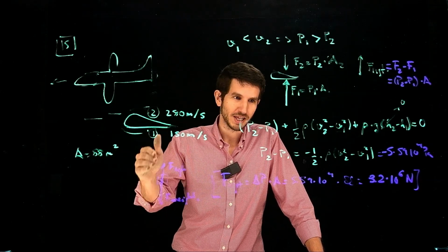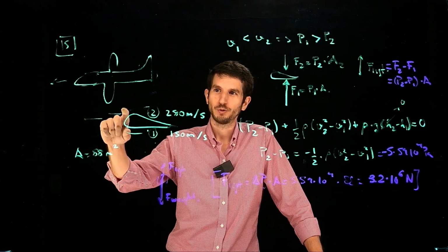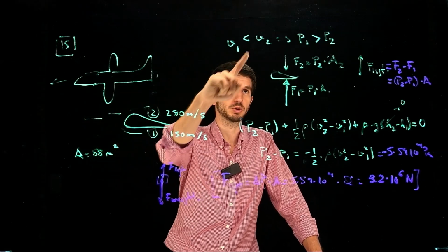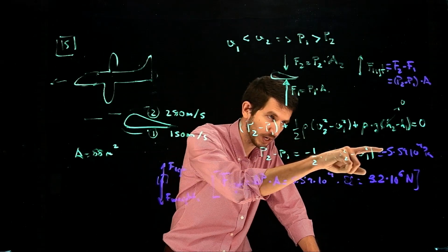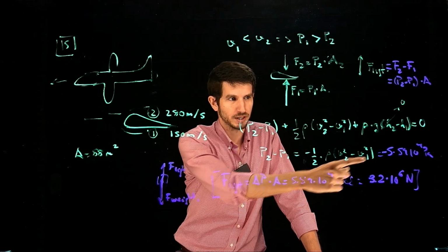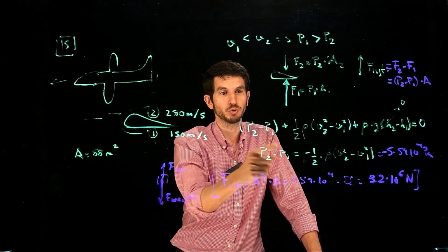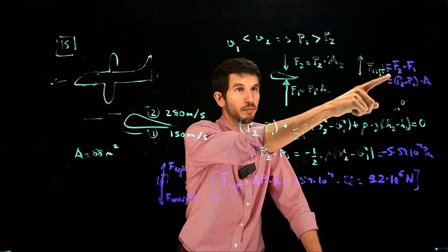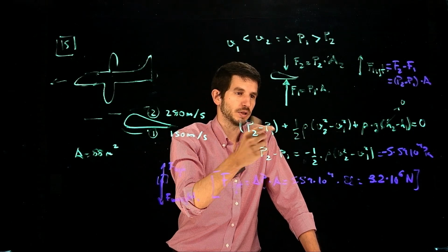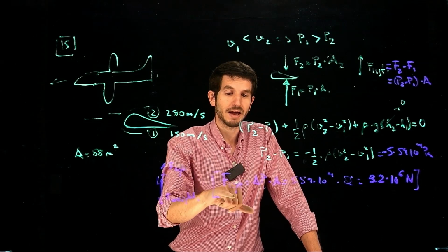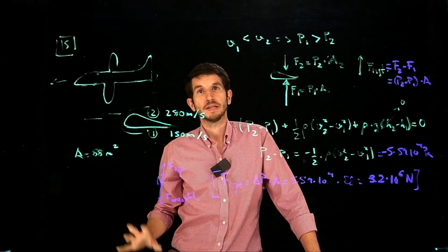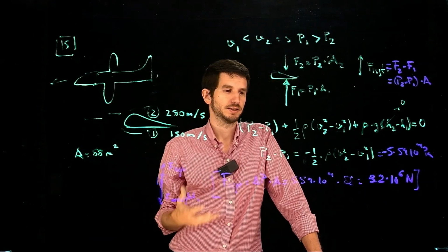So that's another idea in here, right? We see that with fluid motion, we can control the velocity depending on the angle of attack. That generates different velocities, which through the Bernoulli principle mathematically translates into a net pressure pointing up. If we take that pointing up, it was negative because of this difference, F2 minus F1. In reality, this is F1 minus F2. F1 is positive, F2 is negative, and that's why. Eventually we have this lift force, which is 3.2. If you divide by 10, that gives you the maximum mass that this object will be lifting